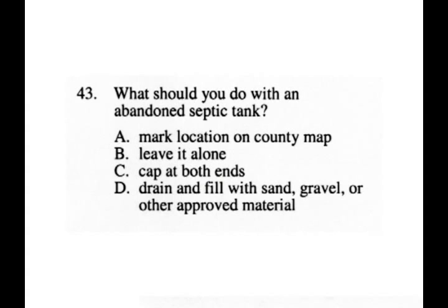Number 43. What should you do with an abandoned septic tank? The answer is letter D, drain and fill with sand, gravel, or other approved material.